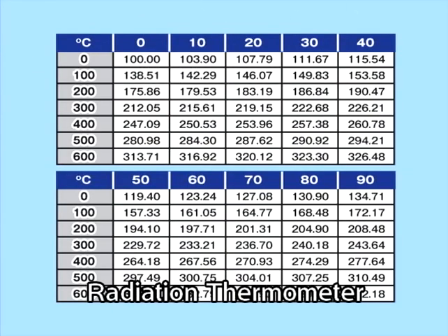The electrical resistance of metal changes with the temperature. The resistance thermometer makes use of this property. High-purity platinum wire is often used because of its heat resistance and stability. Its scope of measurement ranges from -200 degrees Celsius to +600 degrees Celsius.